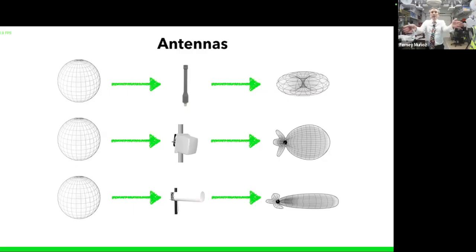Those have a really narrow beam width, and then they go at 5 degrees, 7 degrees, just a smaller beam width. But that's what allows these point-to-point connections to go 20, 30 kilometers on a point-to-point link, because you're focusing the energy on a small area, and then you aim it straight at the other one, and then you can establish these point-to-point links at long distances by focusing the energy.